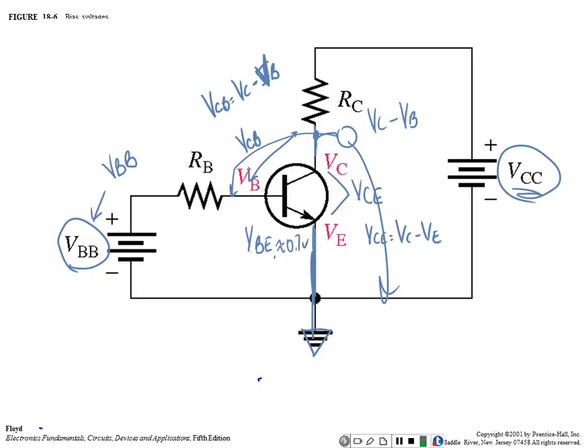And by the way, that's the way you determine if they're operating okay. If the bias voltages are where they're supposed to be. If they're not, then you troubleshoot it. If they are, then you move on, right? Because that's not your problem.